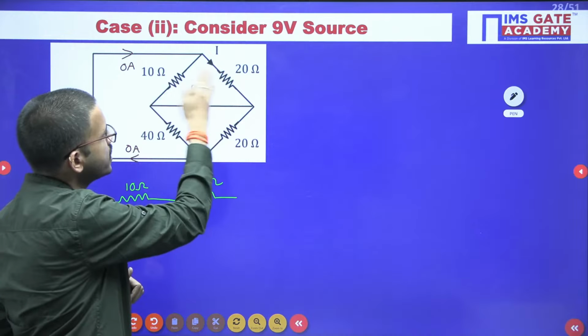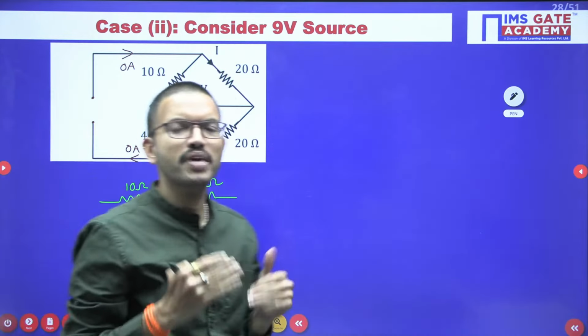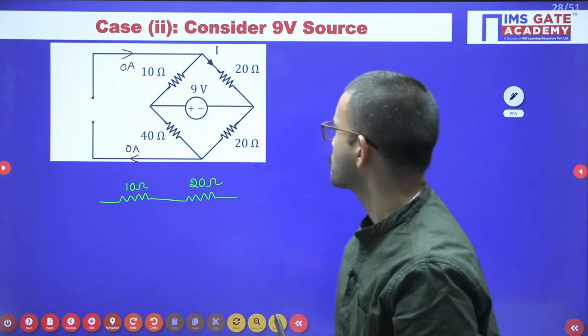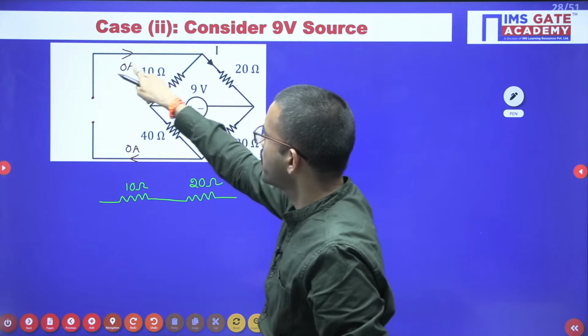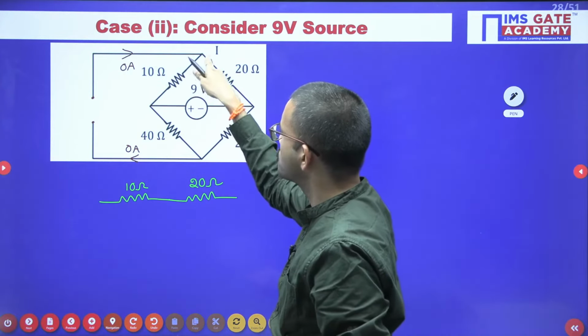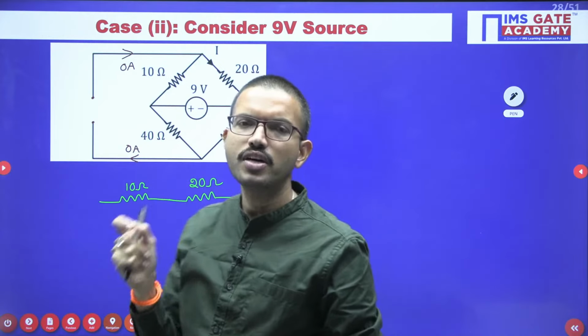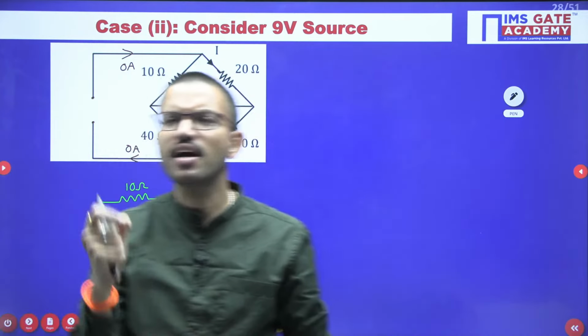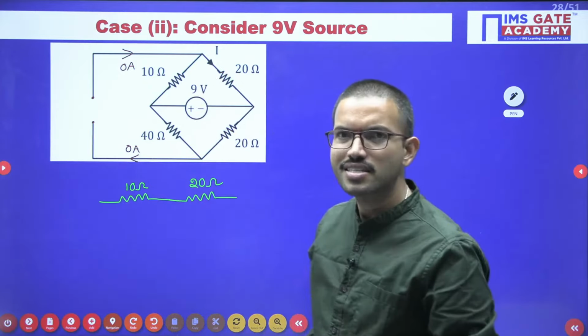Accordingly, different current may flow or the same current can flow. That is based on the given resistor values, according to the voltages, etc. But here, even though 3 branches are connected to a particular node, the moment one of the branch currents is 0 ampere, you can say that the other 2 branches are simply connected in series, that's all.